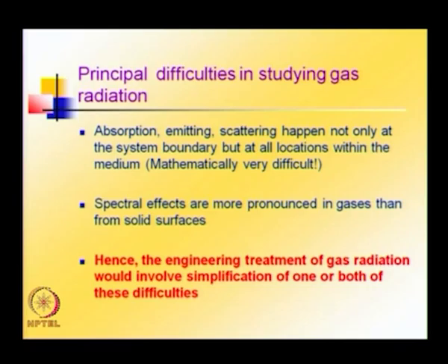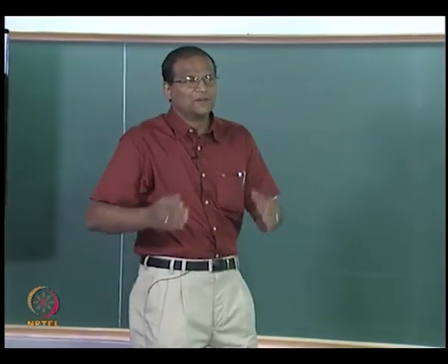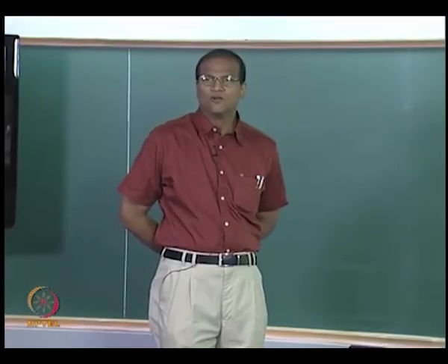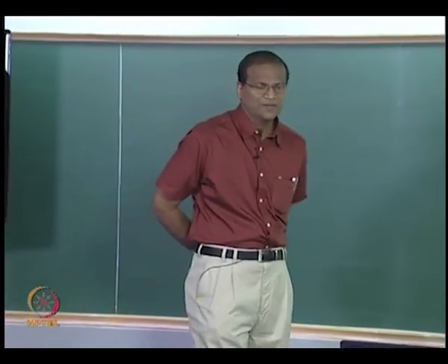However, as engineers we want to solve the problem, we do not want to simply say the problem is very difficult and keep quiet. We want to make some products. So we want some approximate solution. Therefore, the engineering treatment of gas radiation would involve simplification of one or both of these difficulties. I can say that scattering is negligible, or I will say that in the spectral region of interest it is grey. So I will do one or both of the simplifications in order to make the problem tractable.